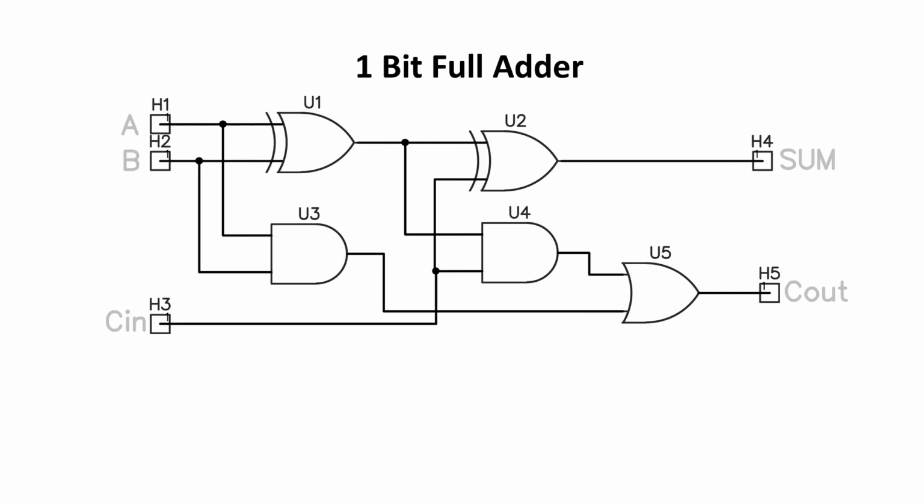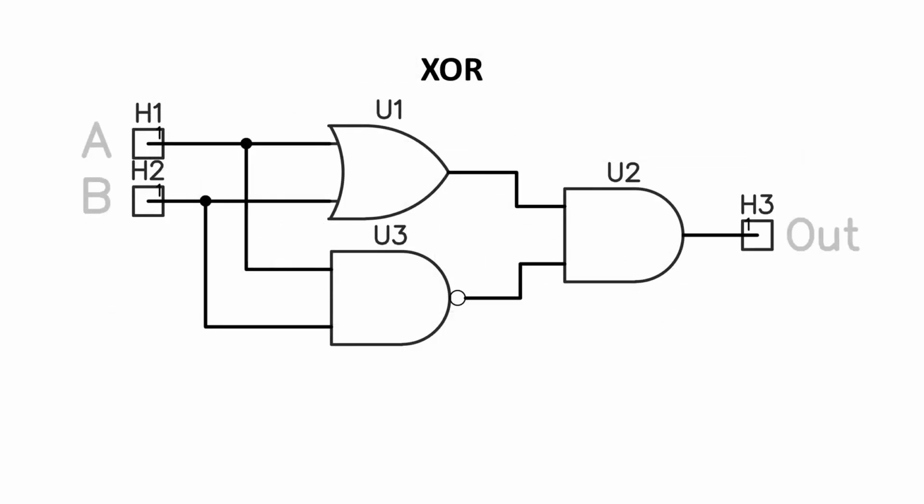Now, one thing about this circuit is, if you're doing this with ICs, it's fine, but if you're doing it with transistors, doing an AND and an OR is quite easy, but a XOR gate, well, that's a bit different. U1 and U2 are both XORs. There are some straightforward transistor circuits for doing those, but generally, this is what your circuit would be.